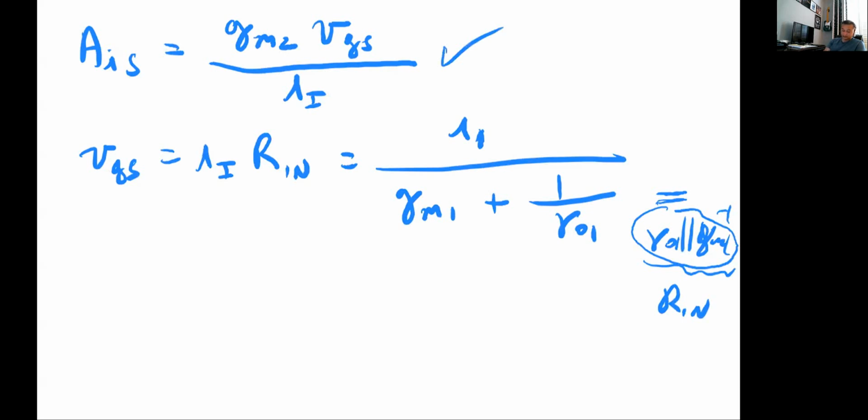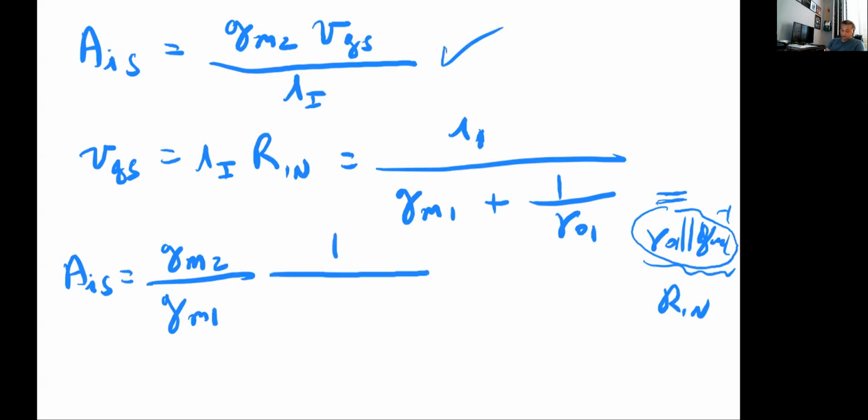So my current gain can be written as gm2 over gm1 times 1 over 1 plus 1 over gm1 ro1, and that is my current gain, okay?